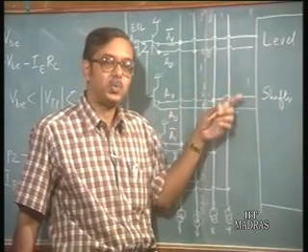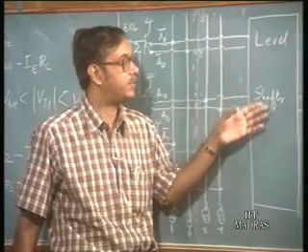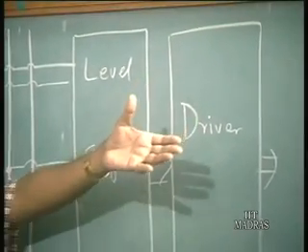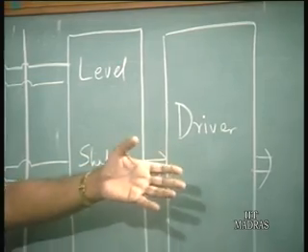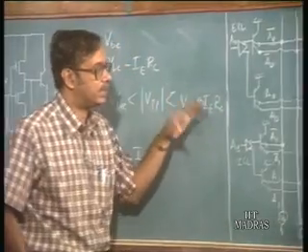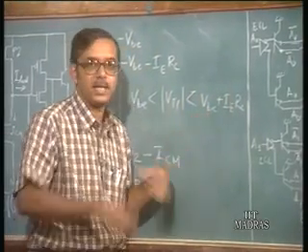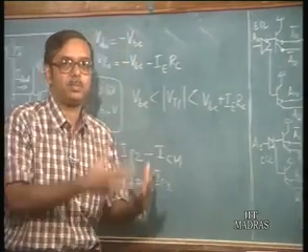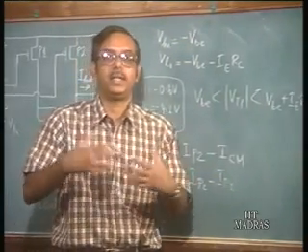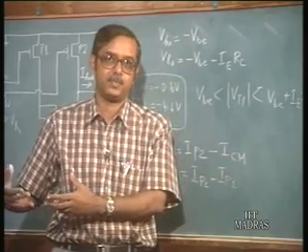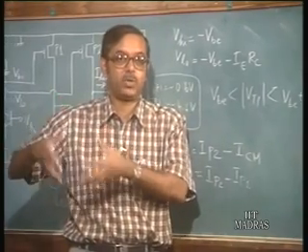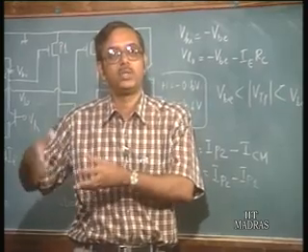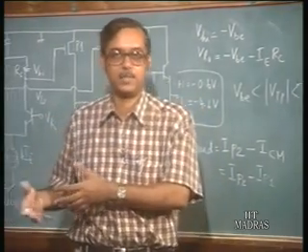Each of these decoder outputs is level shifted, and using a BiCMOS driver you drive the memory word lines. The difference between the 2 circuits is that in one case you convert the ECL levels to BiCMOS levels and then do the decoding at the BiCMOS levels. So the voltage levels of the decoder are BiCMOS levels, and you do the decoding using BiCMOS gates.